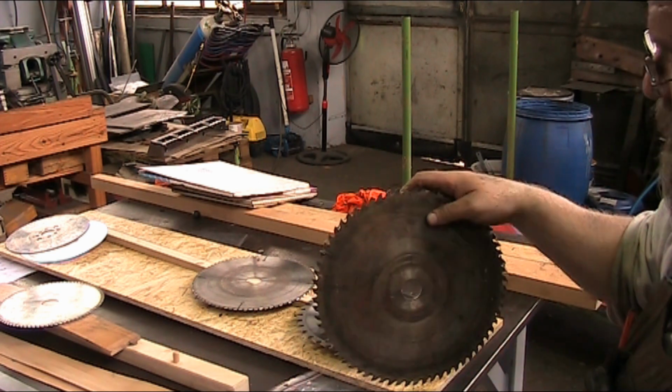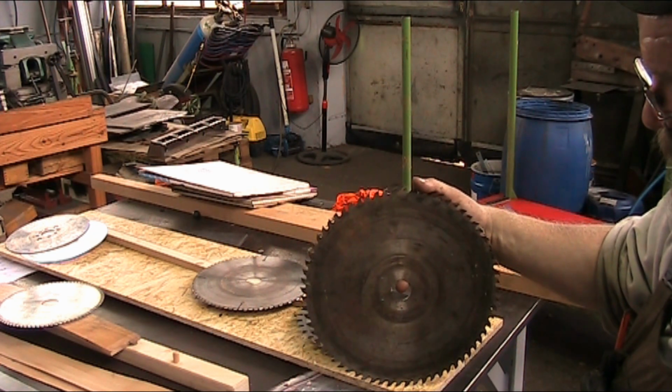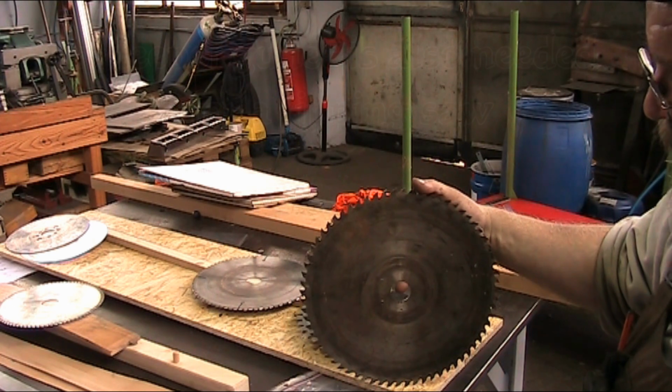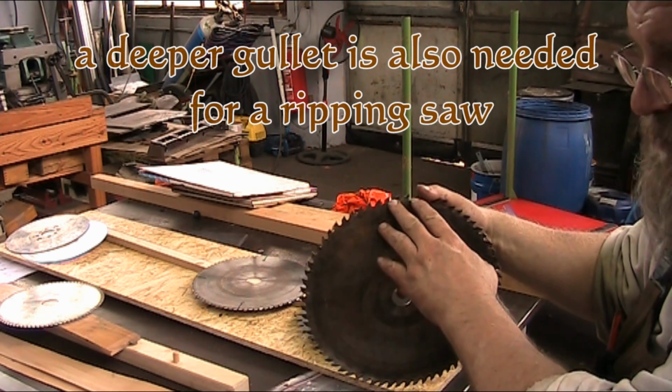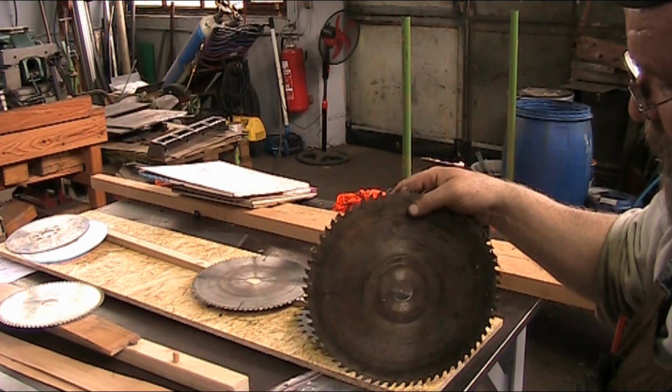So this would be, like I say, more suitable for a cross-cut saw, like a radial arm saw and that sort of thing. For longitudinal cut, you'd need a much bigger tooth with much bigger spacing so that you don't burn up your saw.